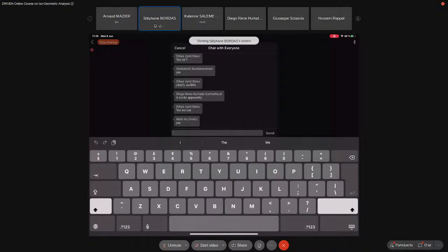The second thing is that once you have done that, you would need to know where you want to put the control points in order to achieve a certain accuracy level. And to do that, the only way I know to do it properly is to have an error estimate. So to have an a posteriori error estimate, which means locally in each patch, you are going to try to compute how accurate the solution is. And if you're interested in this, I can share with you what we did recently on that, because there is, in fact, it's not so recent, an old paper on adaptive PHT splines. And I think that would answer most of your questions. And we could then discuss it, because it's a complicated topic.